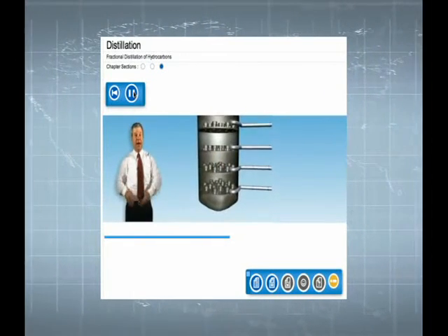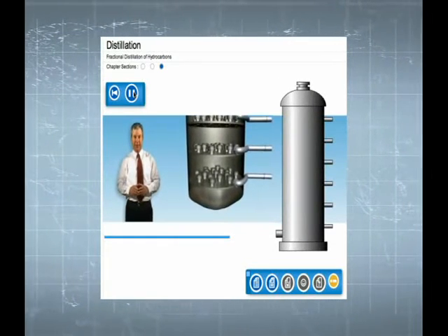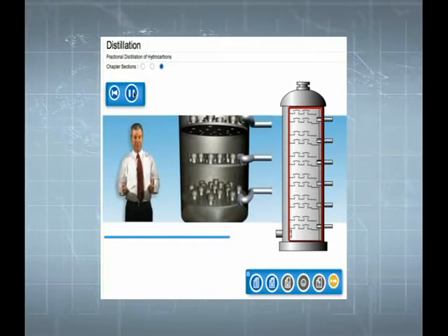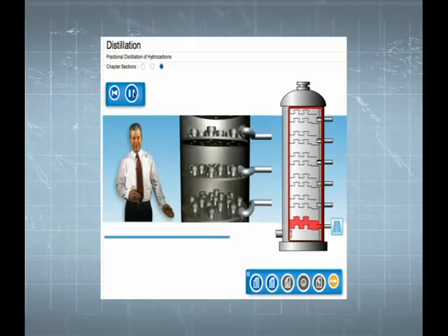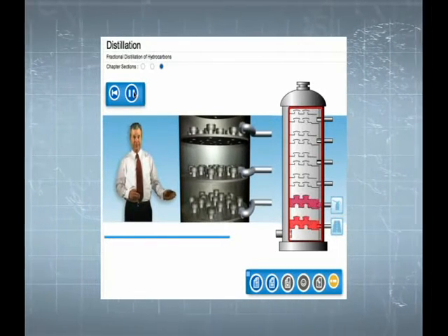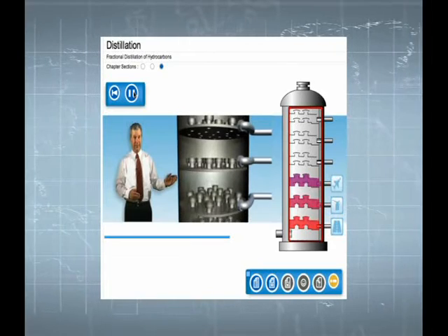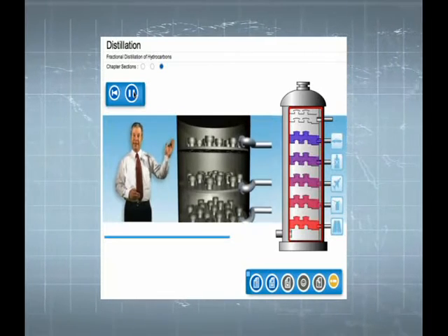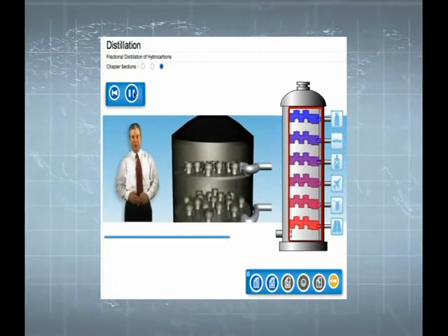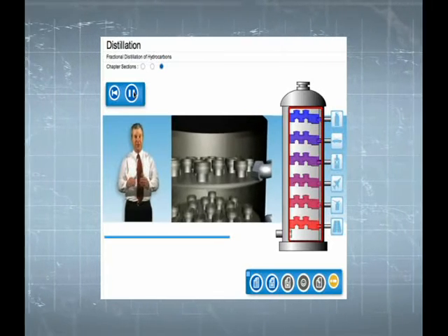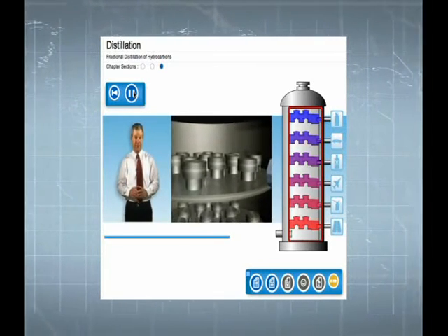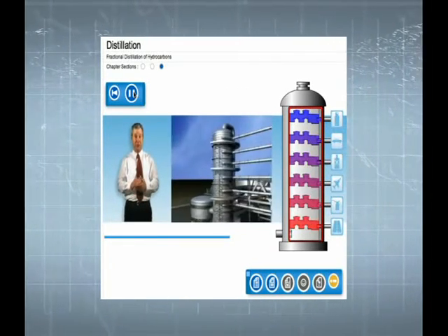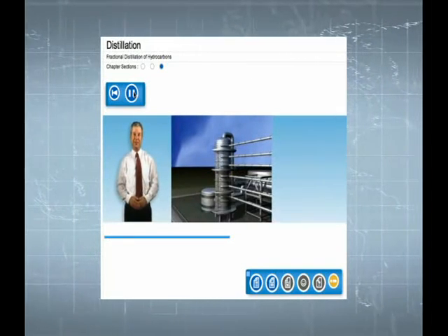So, starting from the bottom up in an atmospheric fractional distillation column, typically vaporized crude oil condenses as follows: long residual fractions, light gas oil, kerosene, naphthas, gasoline, gas. The condensed fractions collect in the trays and can be passed on to condensers, which cool them further. They are then piped to storage tanks, or they can be transported to another area in the refinery for further chemical processing.